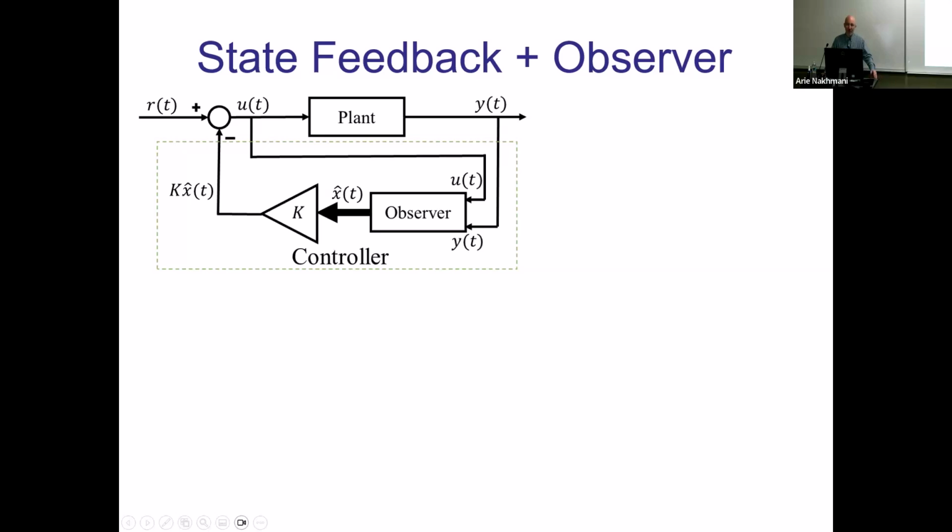So you'll have a transient response which is a little bit longer than if you would connect it directly to the x of the plant. You need to give it time to converge to the real x. But after that, it will start working magically and everything will be great. This is the magic in all of the theory, why this observer is so wonderful.